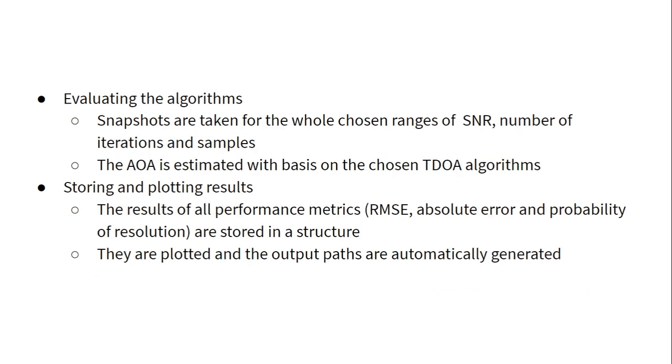So then we evaluate the algorithms. The simulation is executed in snapshots, so we sample the source signal. The angle of arrival is estimated through the chosen TDOA methods and figures of merit. And the execution of this snapshot is held for all ranges of SNR, number of iterations, Monte Carlo runs, number of samples, and so on. The angle of arrival is estimated with basis on the chosen TDOA algorithms, just to complete it.